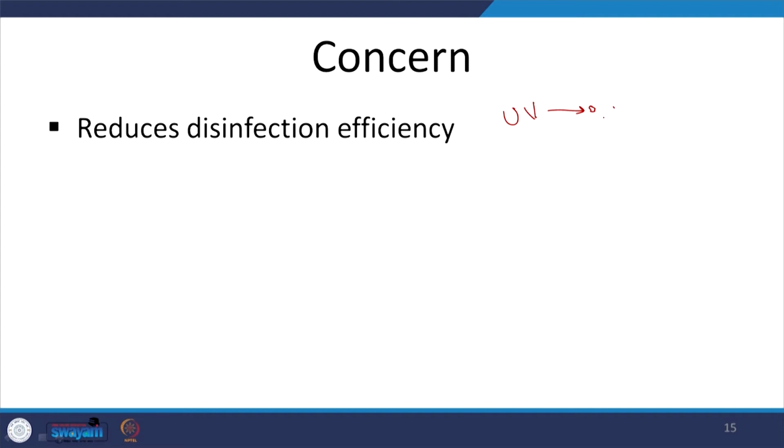Same case if you have organic matter, and I add other oxidizing agents such as chlorine or HOCl or ozone, right? This organic matter, which can be measured indirectly by turbidity, suspended organic matter anyway, will consume the oxidizing agent, thereby limiting the disinfection efficiency. Something to keep in mind.